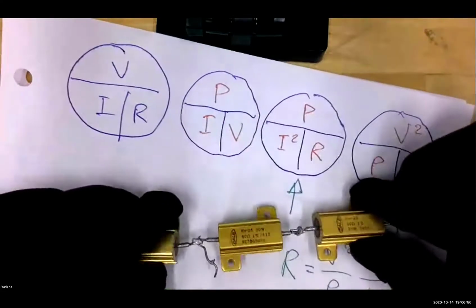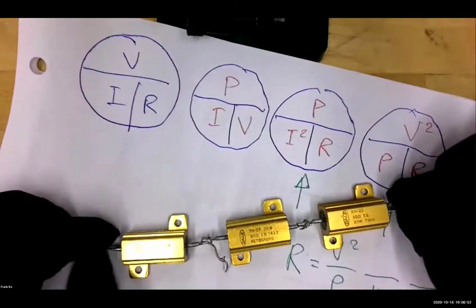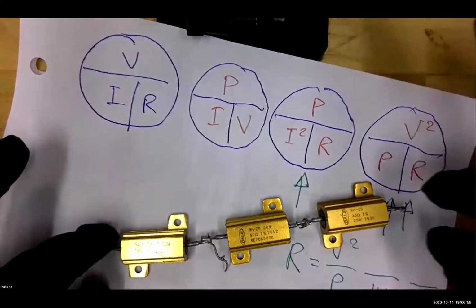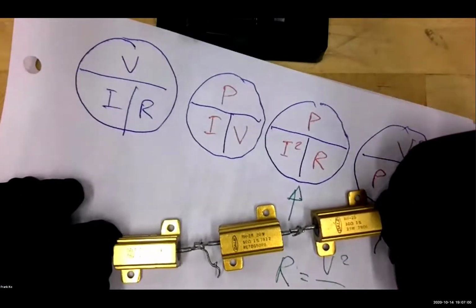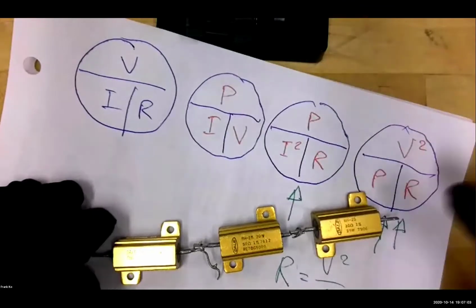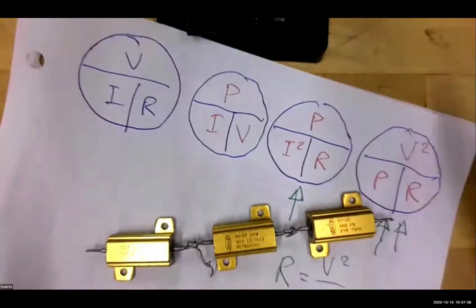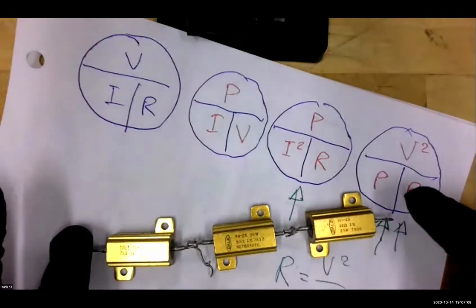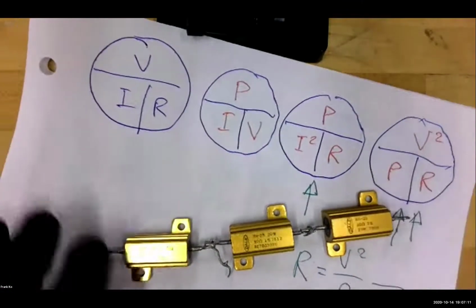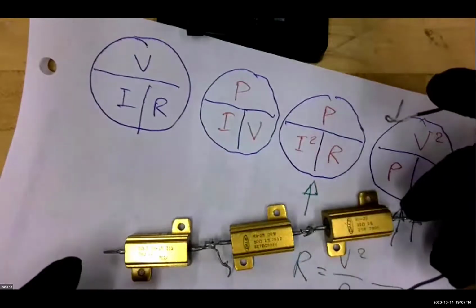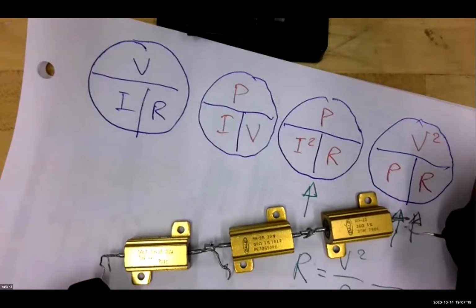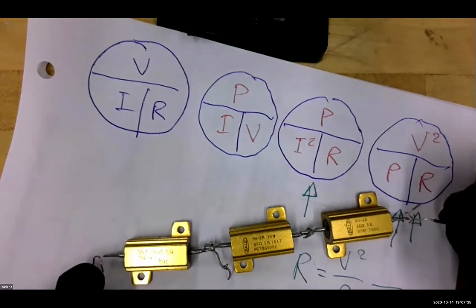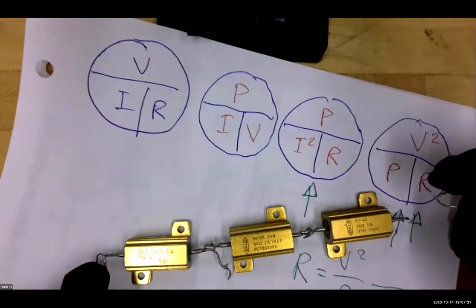So when you go to do this experiment, you want to make absolutely sure you hook up for the shortest period of time possible. You make your measurement in the shortest period of time possible. You write down the values as quickly as possible. Then you disconnect. Because the longer you leave the wall wart in place, if I connect these wires right now, these wires that we have, and I go to connect them here and hook them up with my voltmeter or my ammeter, these will get hot. And they will get so hot that it can burn you. So it will get hot, but that's why you want to make your measurements very, very quickly, okay?